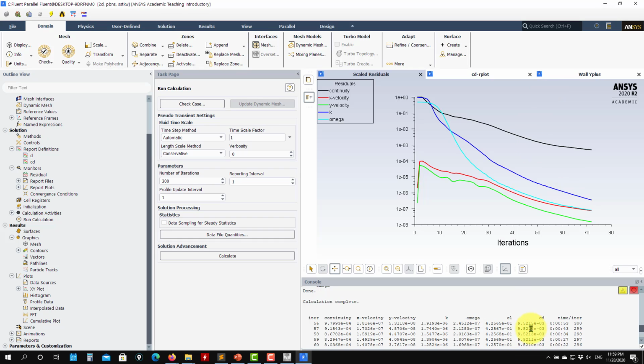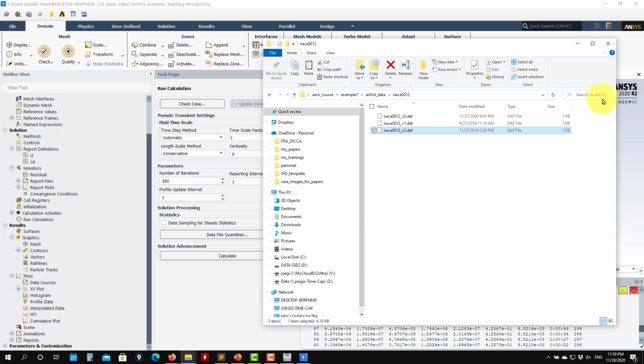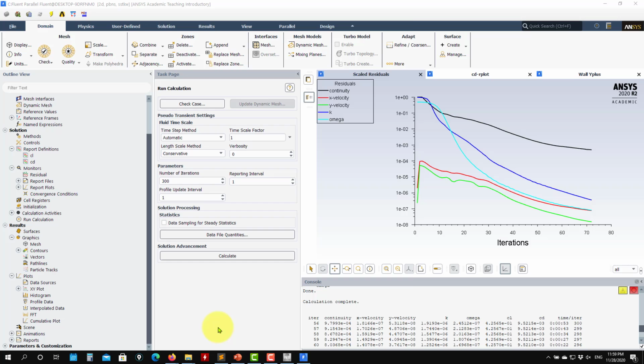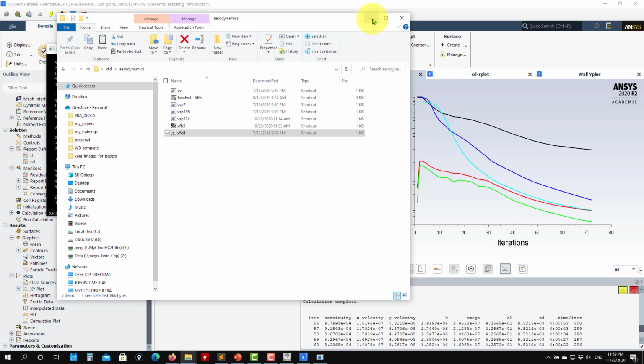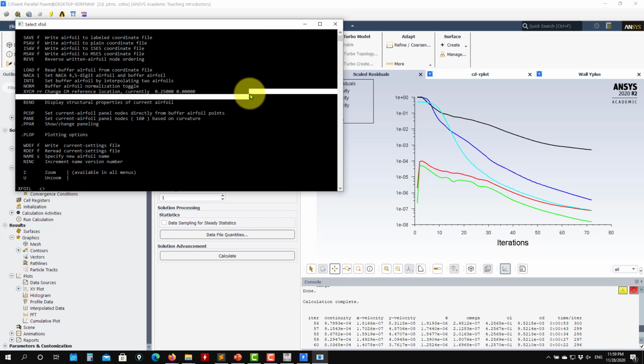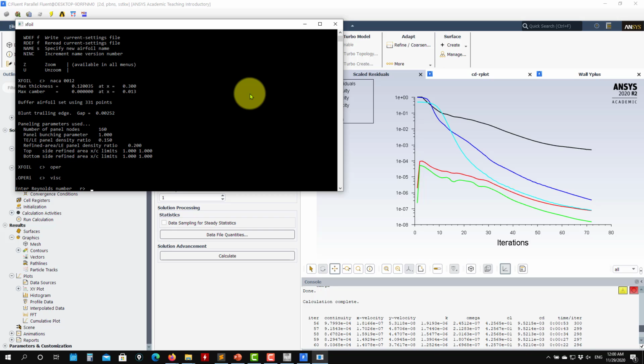So let's do something now. Let's compare Fluent with Airfoil. This is what I'm asking you in the exercise: the same airfoil that you used, run in Fluent, and let's see how close you are. I'm not expecting to have the same value, by the way, but something close. So let me run 0012, upper, Reynolds was 6 million. See here that we don't need to give velocity or anything else, only the Reynolds number, and then give a solution.